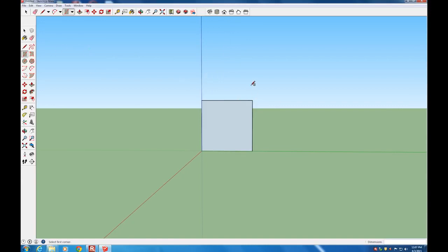So now we're going to add a back to the chair. So I'm going to go over and click on the Line tool and start from this corner point. Notice it highlights the endpoint to show that it's inferencing off of that. Draw up vertically 0.5 meters. So draw in the direction you want to go, type 0.5, click Enter. And then from the end here, we're going to go over 0.1 meters, and then straight back down to the base.